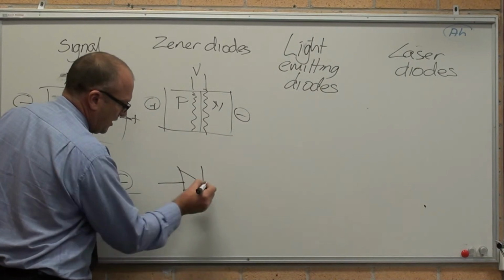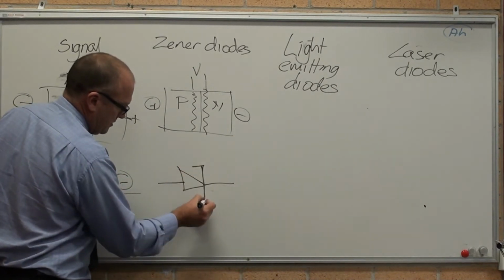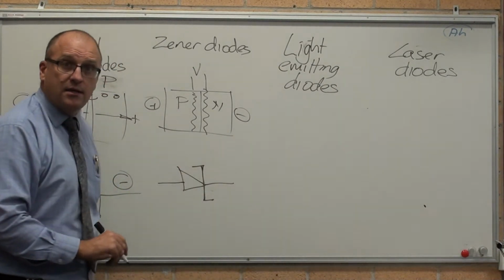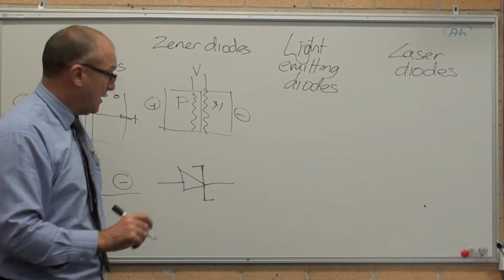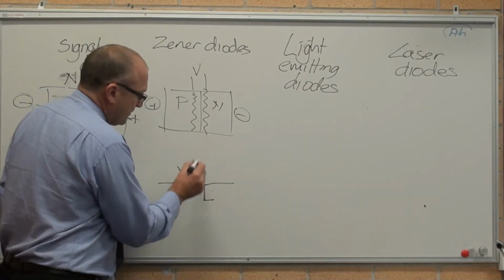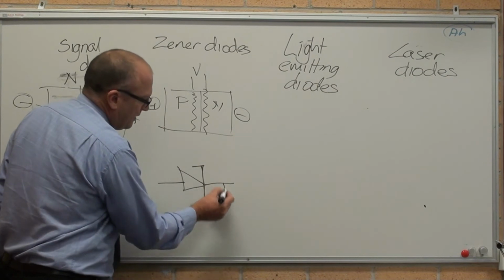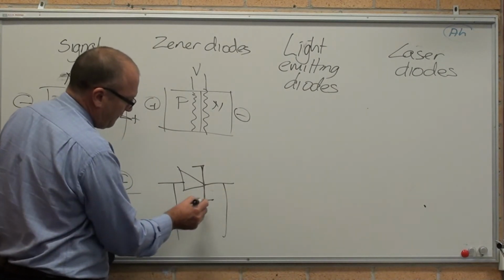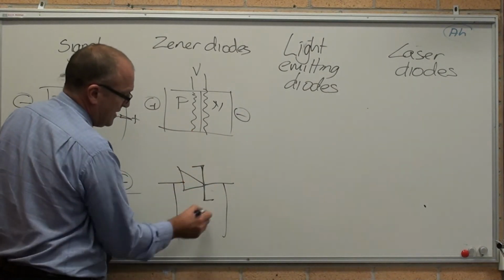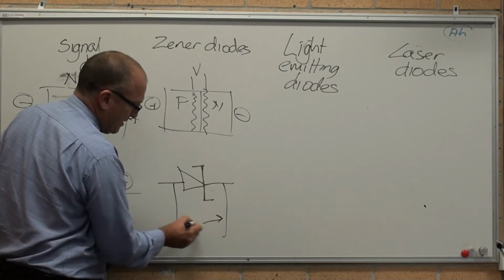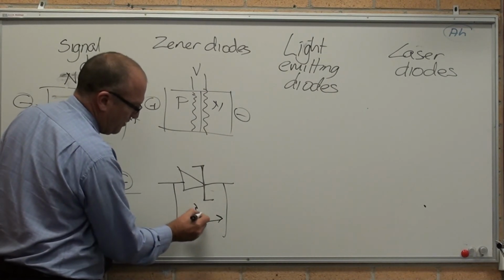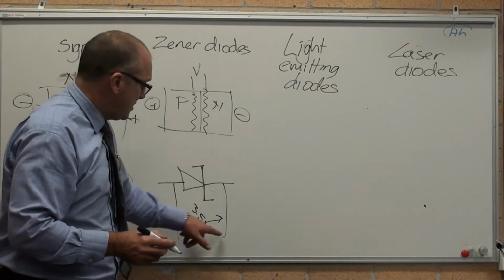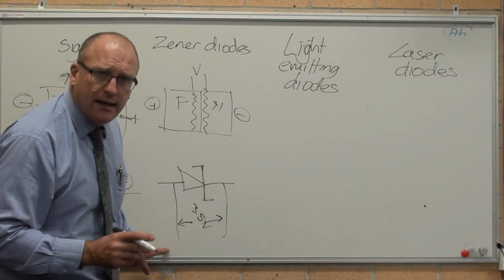That's your standard diode. That looks like a letter Z, doesn't it? That's a Zener diode. Here, let's say that's a 3.5 volt. The voltage across here is an automatic 3.5 volts. So you can use this as a voltage regulator to feed